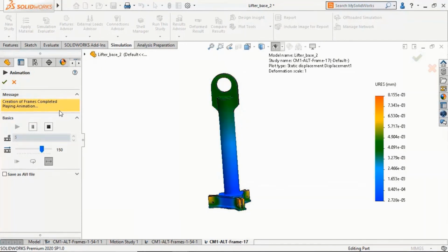So now I started the design from a problem, then an idea. After that, we worked on that idea and made some assumptions for it so that the geometry resulted. We took this geometry to test it kinematically in SOLIDWORKS motion simulation to check if the mechanism is working properly or not. Then we took the data from SOLIDWORKS motion simulation to SOLIDWORKS simulation to check if the final design will withstand the boundary conditions or not. And we found that the final design will withstand the boundary conditions.